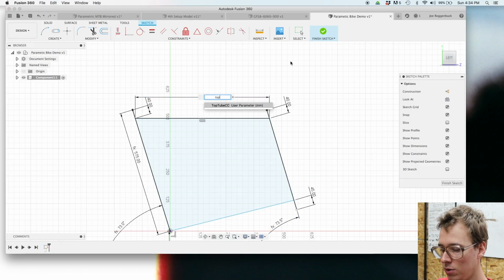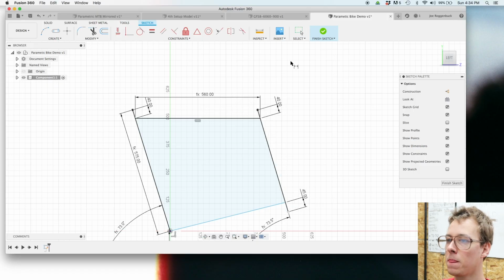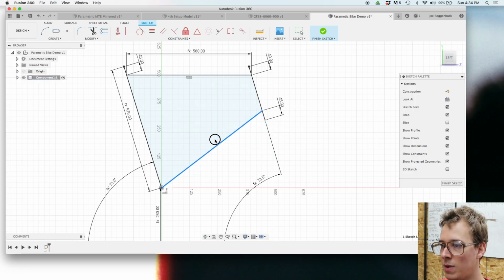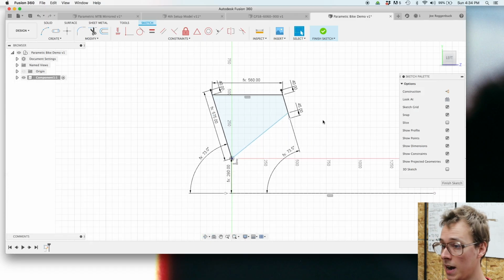This is the top tube length. So now here we have the down tube. I don't want to define the down tube angle. The down tube angle is a driven dimension, really. It's based on some other things. I don't want to define the head tube length, at least not for this bottom location. That seems kind of irrelevant. And so I need to know how far up does this bottom of the head tube come. I'm not going to worry about that just yet.